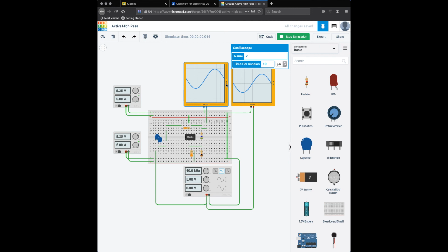Well, it's not exactly doing what I wanted it to do. Ha ha ha ha. At first I thought, well, this is bad. This is what I'm expecting to see. I'm expecting to see my input signal here on the right-hand oscilloscope, and my output signal should be reduced because it's been filtered by 70%. So it should be smaller, and yet it looks bigger, but you can tell that the reason for that is this is 10 volts on this scale, and this is 100 nanovolts on this scale. So it has been reduced by the scale, but there's no way to set the vertical